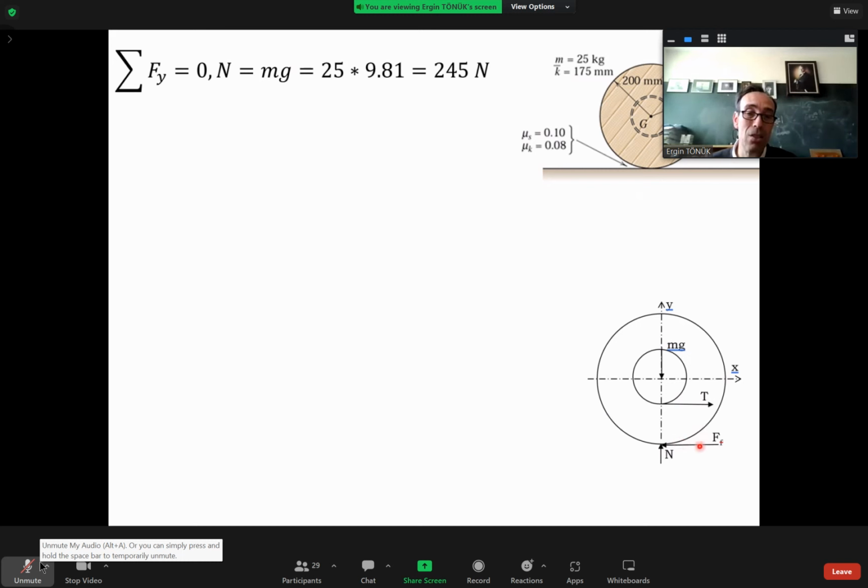Actually, in such a case, what you would do is you may just put friction force in one direction and try to compute its value. Then also you have to compare it with the maximum friction force. There will be actually two components of the friction force. One would be to slow down the acceleration of the mass center, which would be to the left.